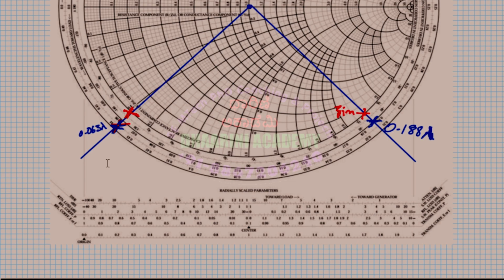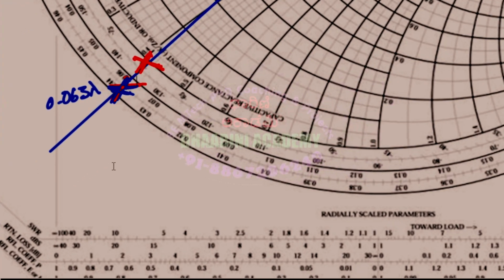So we will read out that point. It is again below the horizontal line, so it is always lesser. Maybe this is slightly below the 0.4. So 0.4 and 0.5, it's the middle, right? I can simply write this value. This is the ZL value. ZL is equal to minus j, because it is below, right? j 0.4.